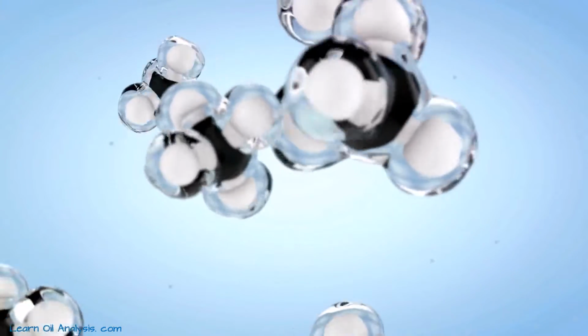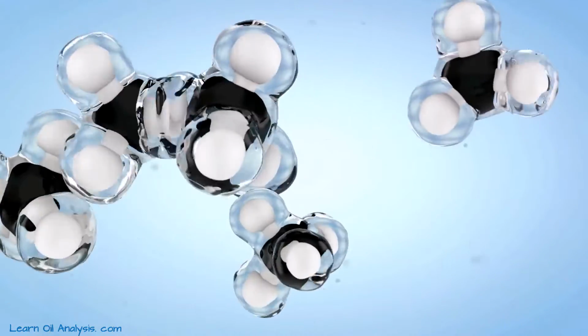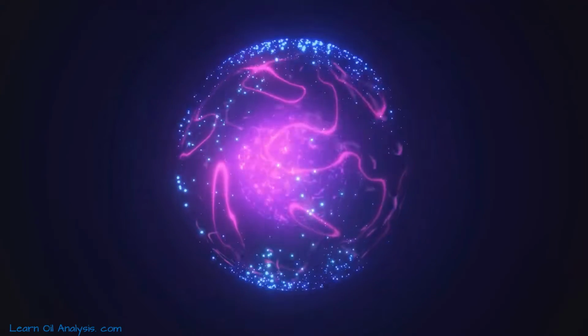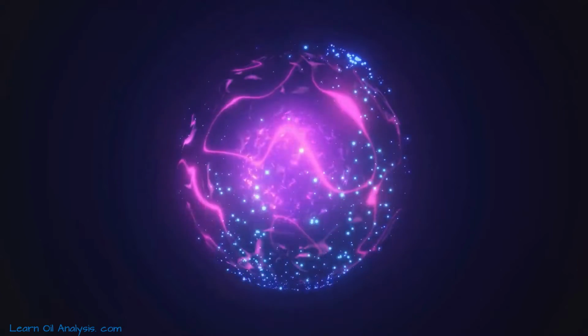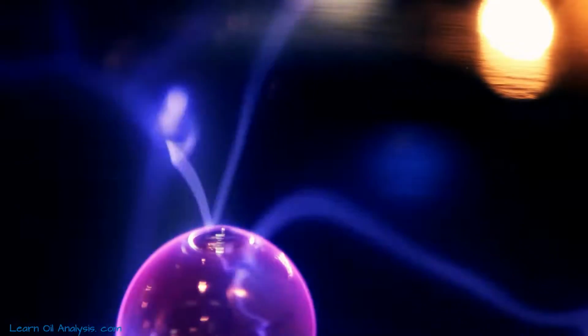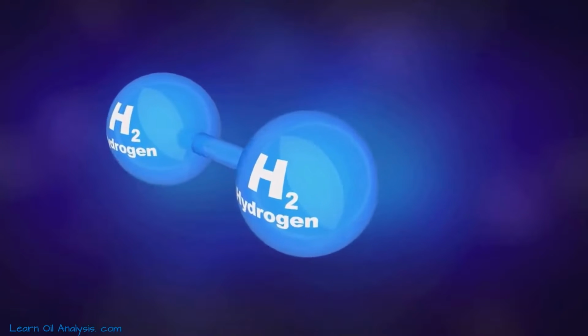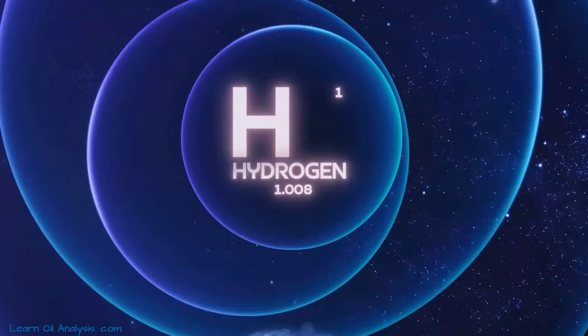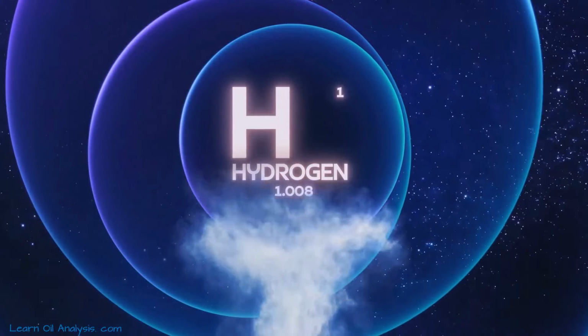Our first stop on this journey is partial discharges. Now, this is a type of fault that occurs within transformers, within the gaps of insulation such as an air bubble or small sections of the fluid, but not allowing continuous discharge between the metal contacts. Think of tiny storms within the oil. Hydrogen is the key gas here. Hydrogen is produced as carbon-hydrogen bonds and water molecules are cut off by these mini lightning storms within the oil.